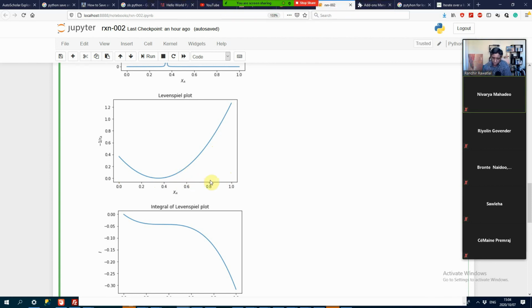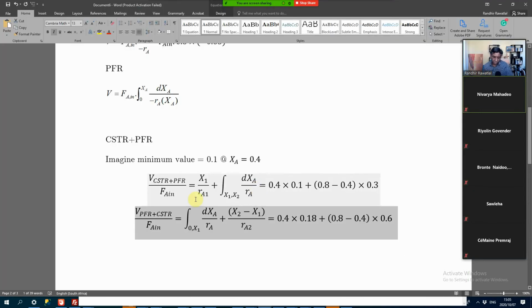So when you put it second, your reaction rate in the CSTR, even though it's the same CSTR, is lower there. And you could make similar arguments about the PFR. So it's not just a mechanical thing. The order matters, and it's not just mathematical. It also, in terms of kinetics and navigating the plane of kinetics, makes a difference there.